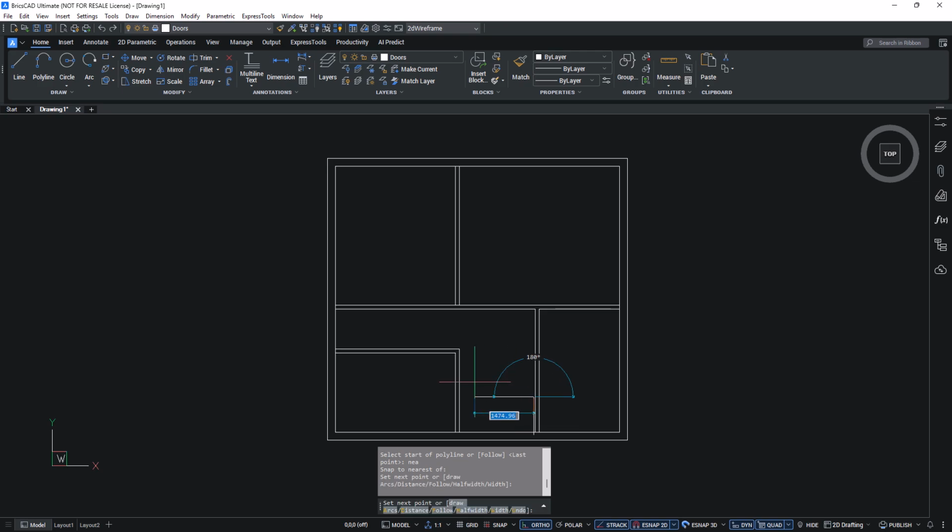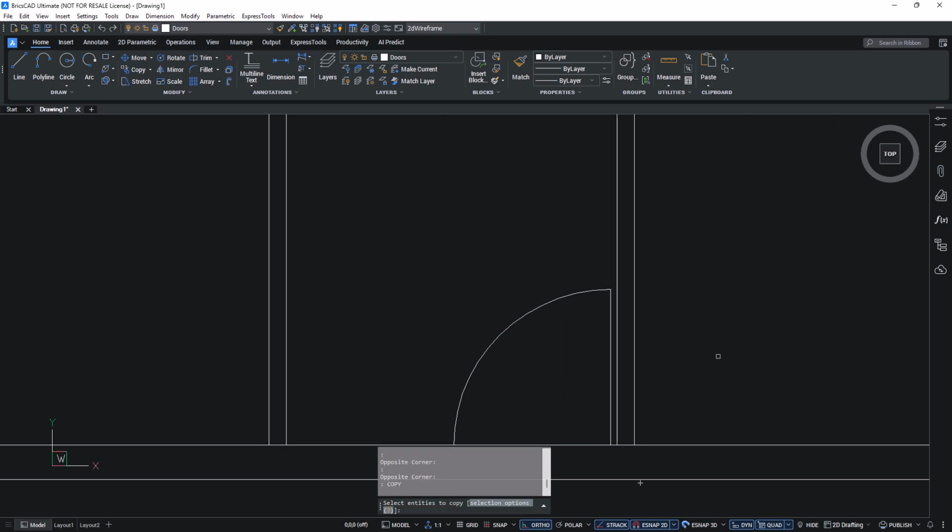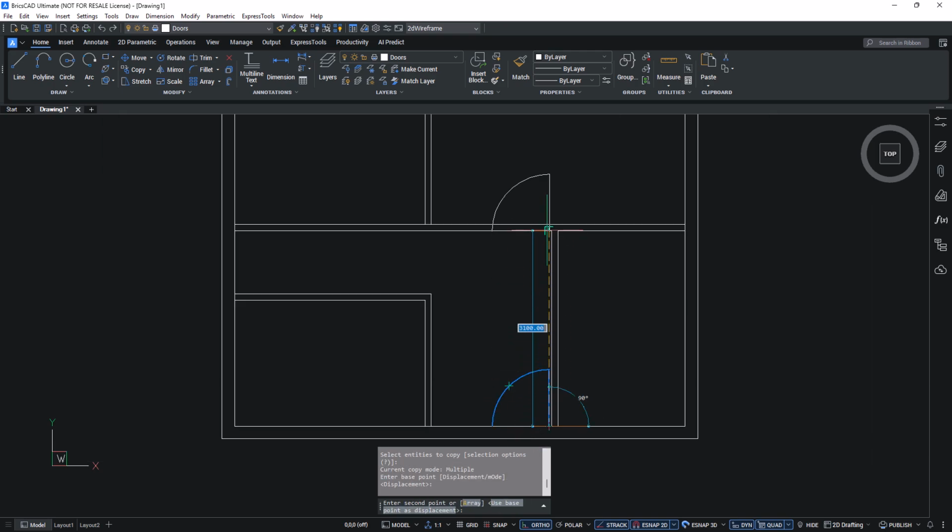Enter 900 for the door dimension. Then click the arc option and select the center option. Click on the door starting point and click on the left side, then press Enter to finish the command. The Copy command creates a copy of the door on the internal wall.